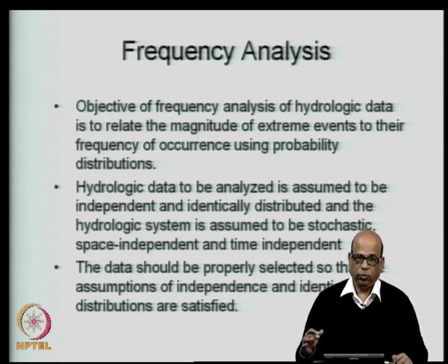But in this course, for the time being, we are focusing on at site frequency analysis, where we will be collecting data from a given stream gauge or given rain gauge, and then we will be carrying out the frequency analysis for that particular stream gauge or the rain gauge.